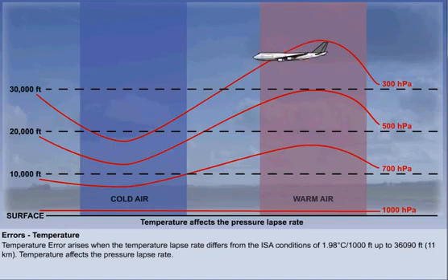Let's now fly an aircraft from the right to the area on the left at a constant indicated altitude. To achieve a constant indicated altitude, the pressure sensed by the altimeter must not change. In other words, we must follow a pressure level. However, in doing so, we are inadvertently following a pressure level which is actually descending, so in reality we are descending also, but the altimeter is not showing this. Our true altitude is decreasing, but our indicated altitude is constant. This is a dangerous situation.